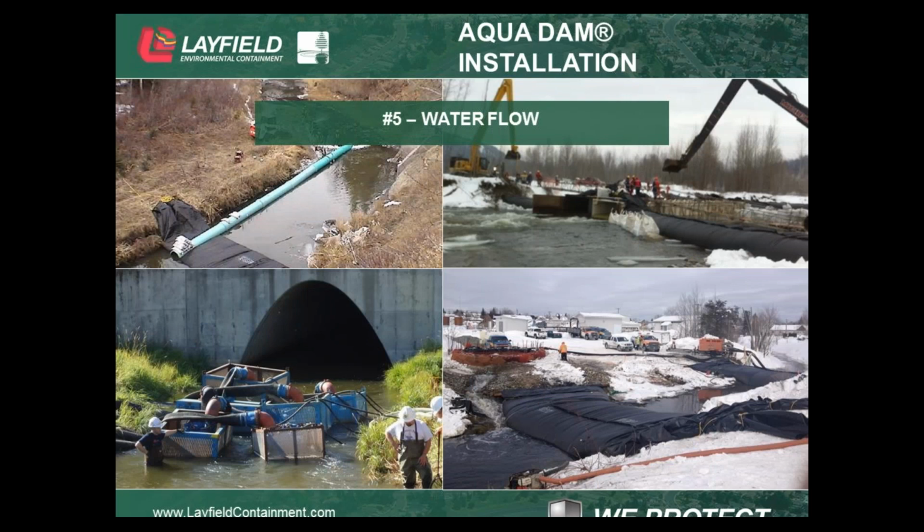So once we got the aqua dams in place, then we got to worry about how we're going to deal with water flow. How are we going to divert the water around your work site? There's different methodologies behind that, everything from pipes to flumes to pumps to diversion channels. You can see in the top left, in this installation, they've utilized an 18-inch diameter pipe. They've weighted it down on top, and they've got water diverting around their work site through that pipe. In some scenarios, we've actually run a couple of aqua dams and run the piping underneath the aqua dam.